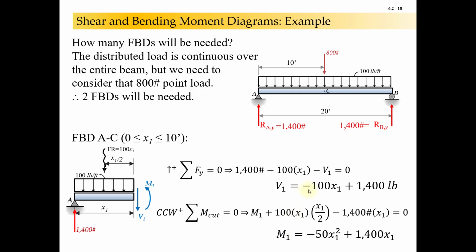We usually recognize that, and like I said, when you get to these graphical methods, that becomes very important to recognize. But don't think you're going to be using your calculus to integrate your shear to get your moment, because sometimes evaluating that constant of integration can be quite tricky. It's much better just to use the equilibrium equations that you have learned here in the statics course.